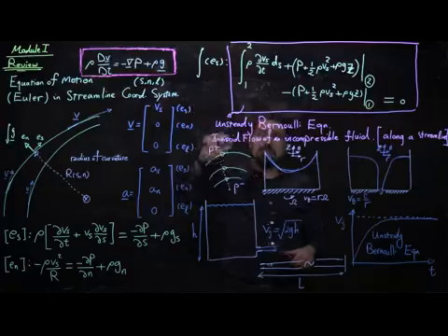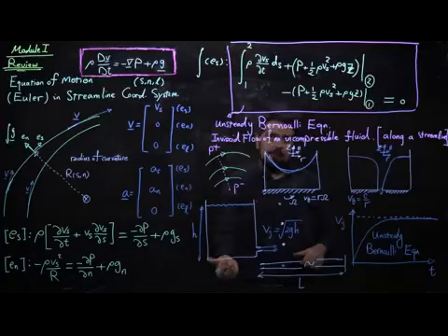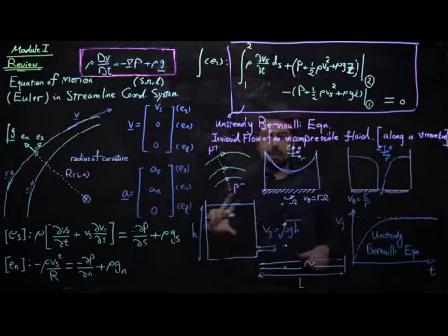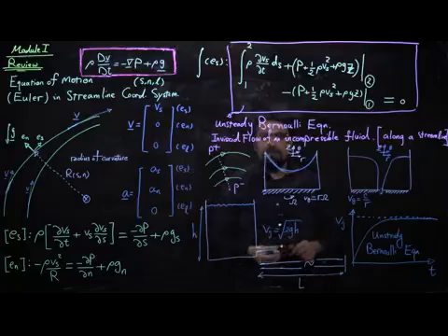And we found out that in certain cases, we can apply it in a steady form, and very easily we can find a connection between hydrostatic pressure or height and velocities by just using the principle that whatever potential energy fluid elements have here, it gets completely converted into kinetic energy as they exit the nozzle.